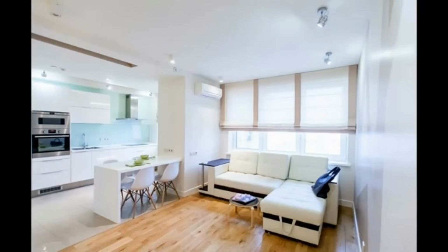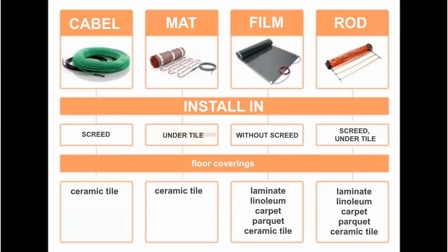Disadvantages: cost significantly higher than film solutions, and many unverified products on the market, so you can easily run into a not so high quality product. Also, the disadvantages of all electrical heating systems: the only source of energy for such floors can be electricity, and the efficiency of such systems is not higher than 100%.